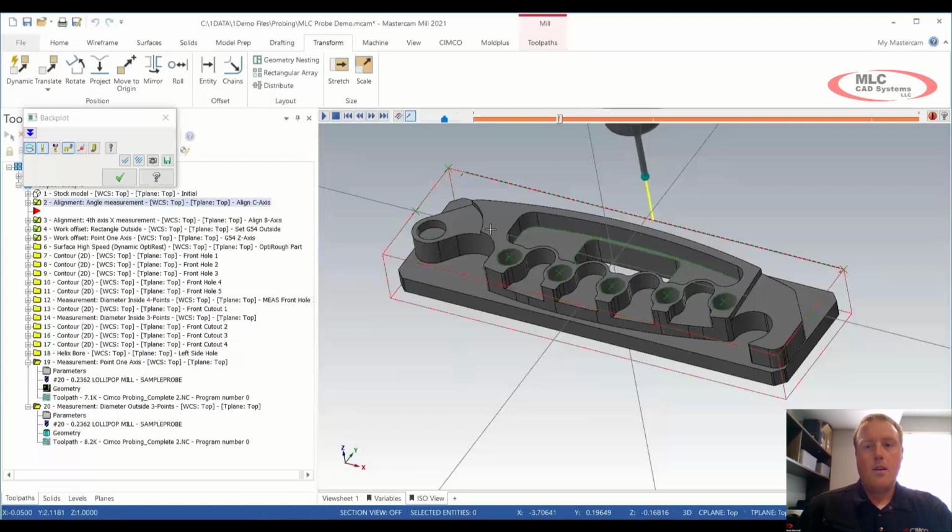variable there. From there, it's also going to go in and do our B-axis, right? So make sure that's sitting flat, followed by going in and doing what we call an outside rectangle feature. That's going to touch on all 4 sides of the part, naturally making the center of the part my 0 location. And then lastly, I'm going to come down in Z, touching off the top of the stock, and calling that my new Z0.